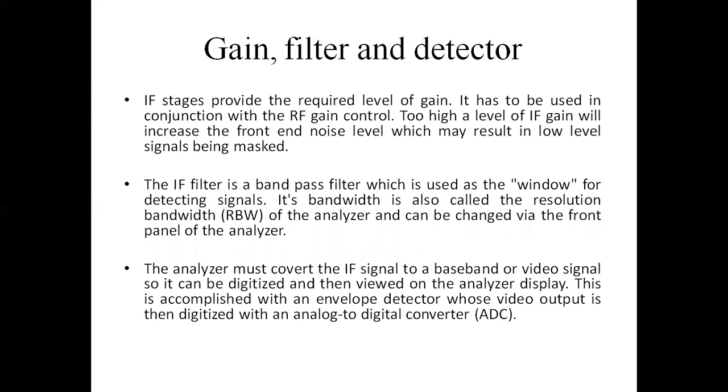Without gain, it's very difficult to display the low frequency signal using a spectrum analyzer. So to boost or improve the input signal, we are using these IF stages. Based on the gain of the IF stages, the signal clarity will be higher. It is used along with the RF gain control. Too much IF gain will increase the front-end noise level, which may result in low-level signals.